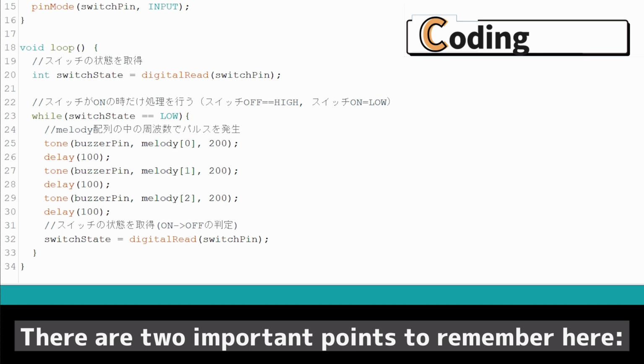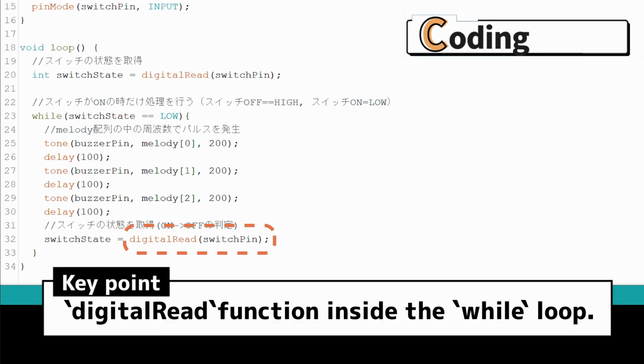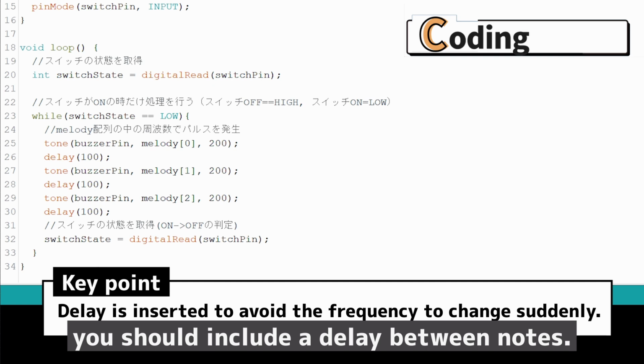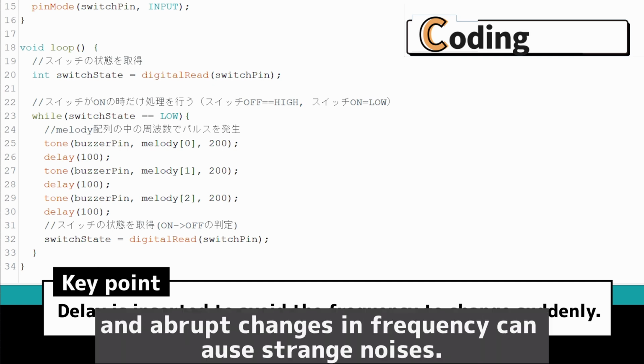There are two important points to remember here. One, you need to include a digital read function inside the while loop to check if the switch is still being pressed. Two, when using the tone function multiple times in succession, you should include a delay between notes. This is because the buzzer creates sound by vibrating, and abrupt changes in frequency can cause strange noises.